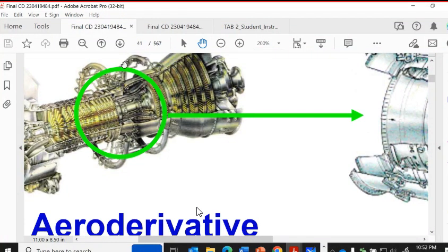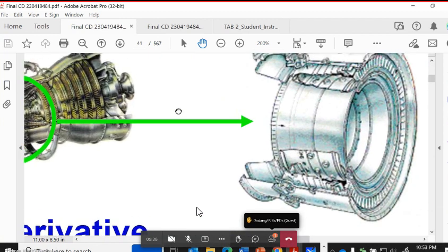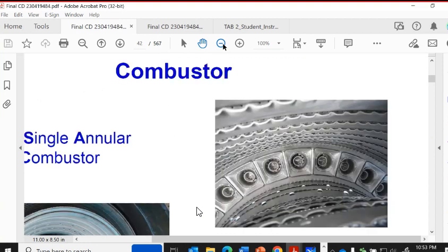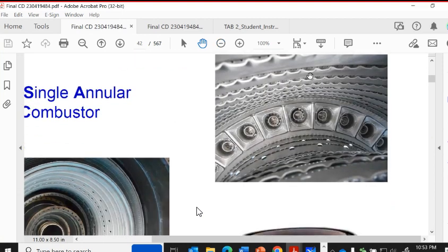This is my gas manifold, liquid manifold, kind of what you got coming into your system. In your case, you have both liquid fuel and gas fuel capability. But this is your combustor can. And if you see here, you got air holes and ridges on the can. You can see a better view of it. But see all the cooling holes that you have through here?